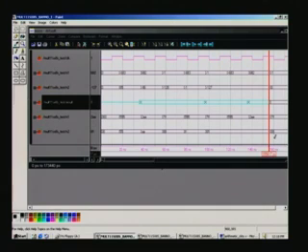Before I zoom, I will just explain what they are. We have seen a total of 8 pipeline stages, that is clock 1 through 8. So, naturally the results will manifest only after 8 clock pulses. Let us first have a look whether it is so. Here we have a waveform, and 3, 6, 7, the 8th clock is here, right. Because it is a back annotated file, naturally the final result must be delayed a bit here.